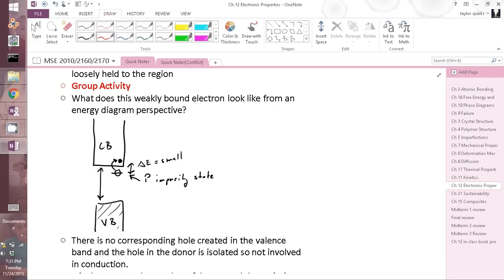On the other hand, if we have boron, what does boron look like in this picture? Boron looks like this. It's an energy level down here where we started out with these filled. Our electron used to be down here, but it hops up slightly to fill this site and leaves behind a hole. So here's our hole left over.